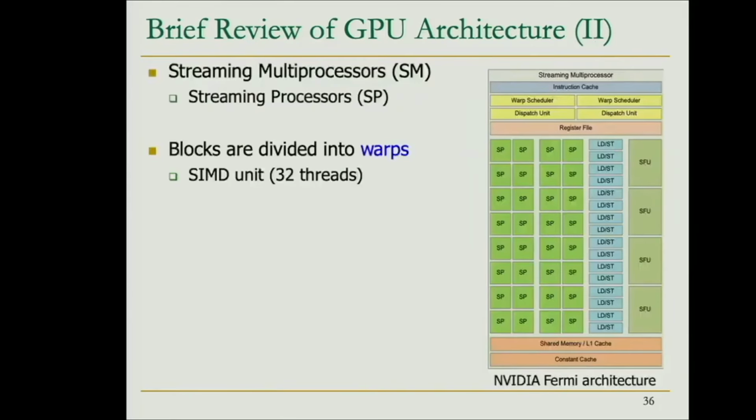And you already saw this slide the other day. This is the NVIDIA Fermi architecture from 2010. In this case, observe that in total we have 32 of these SPs, 32 SIMD lanes, but the way they are used is by using 16 on one side and 16 on the other side. Notice that we have two warp schedulers fetching instructions from the instruction cache, and they are issuing the instruction either on one group of 16 or the other. So in this case, we need 2 cycles to start the computation for the whole warp.